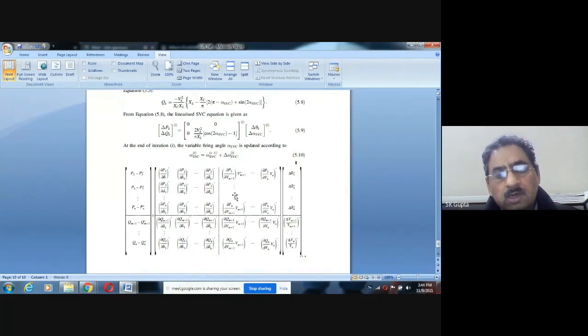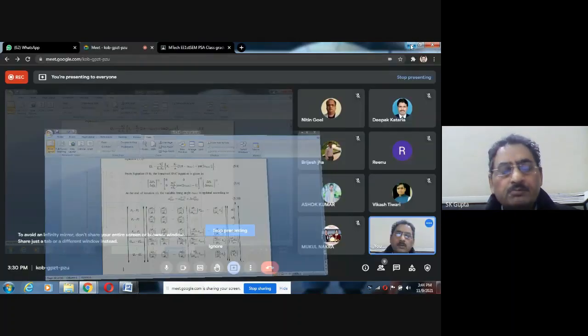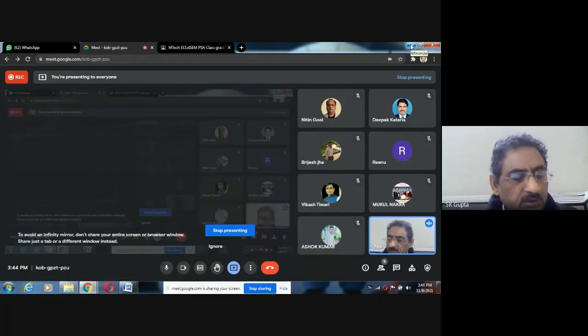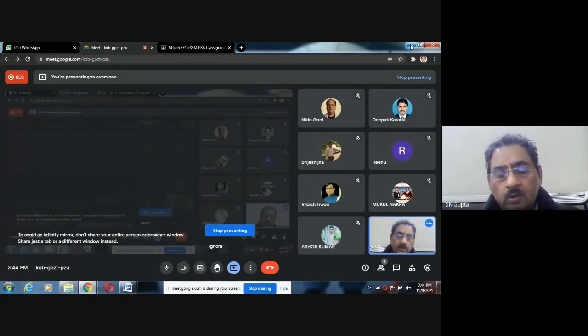So here in the Jacobian matrix in the load flow study Newton-Raphson method, for del Q, one more equation at the kth bus will be added, and that will be given by this equation. In this way we make the change in the Newton-Raphson method to incorporate the effect of SVC, to obtain the steady state values, to make the steady state analysis.